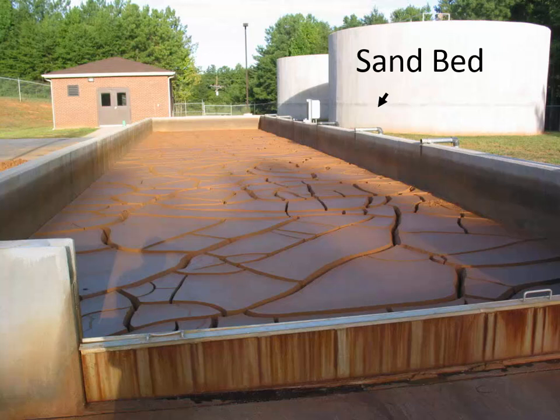So usually it's 2% solid, roughly, in the sludge. This is after it's dried, so this is after the sludge has dewatered. And so there's a lot of volume here that you can tell the water level was much higher than it is now. It started out as 98% water, but the water is evaporating, and so the level gets lower and lower until it's just the solids that are left.